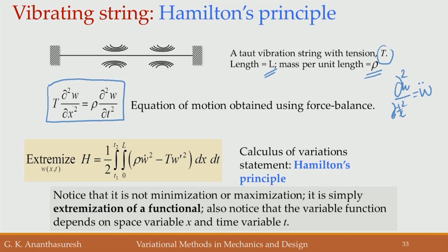Okay. So, this is the force balance, but you can get it in a different way by using what is known as Hamilton's principle, where we have something called an action integral, which is denoted sometimes by A, sometimes by H, where there is a functional. If you notice, this functional has two variables x and t. We are integrating with respect to x and t because our function W here is a function of x and t.